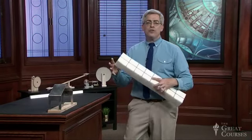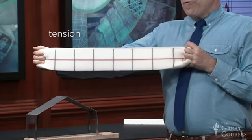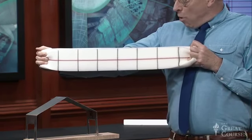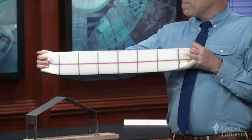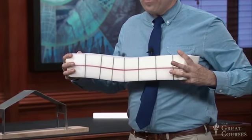First, if the element is stretched like this, it elongates and is said to be in tension. Note that the vertical black lines are getting farther apart as I pull on it. If the element is squashed like this, it shortens and is said to be in compression. Now note that the black lines are getting closer together.